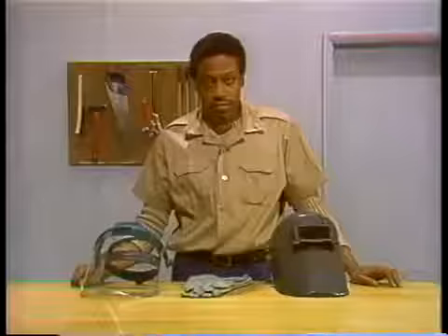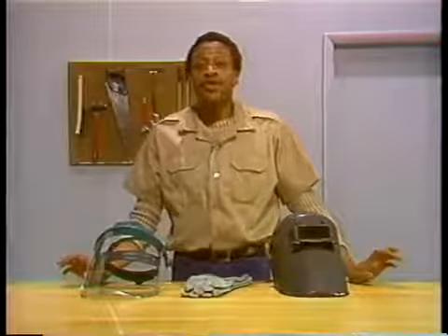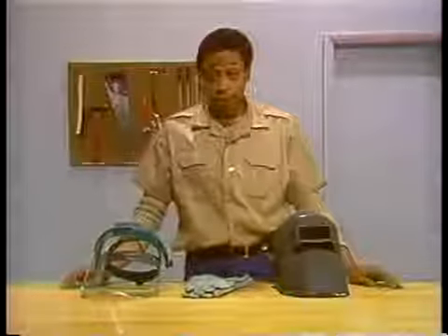That ends our demonstration of window repairs for tube failures. Now we're finished with our discussion of tube repairs in general. You should now know what causes tube failures, what these failures look like, and the 4 ways that failures can be fixed: replacing a tube section, cladding a thinned area, closing a rupture, and making a window repair.